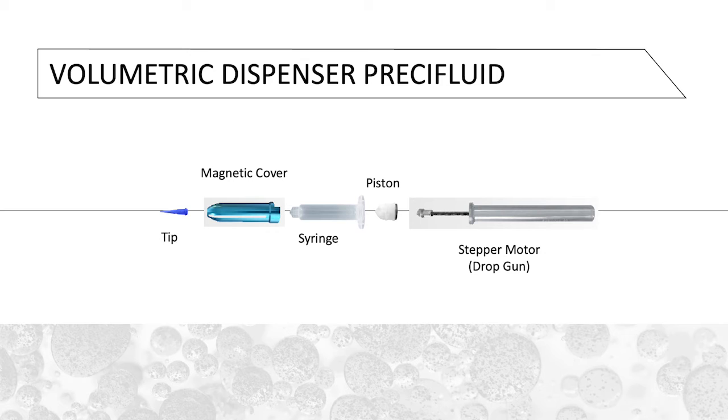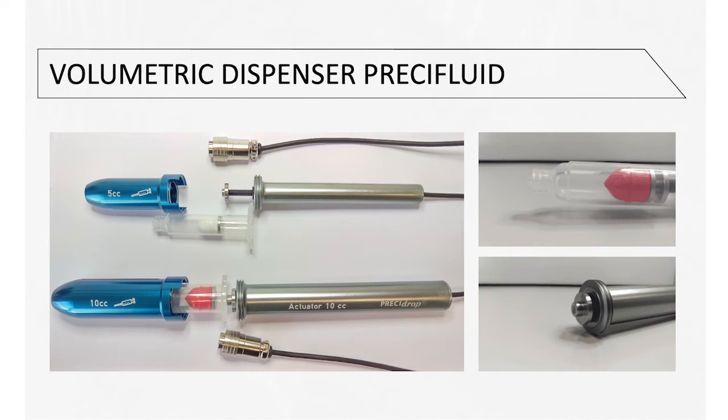A stepper motor applies magnetic force to a special metal attachment in the piston. The piston then compresses the adhesive in the syringe and dispenses repeatable small dots of epoxy. A magnetic dispensing system like this allows for not only precise volumetric dispensing volumes, but for equally precise backsteps, which are critical for forming hemispherical dots and preventing dot-to-dot tailing.